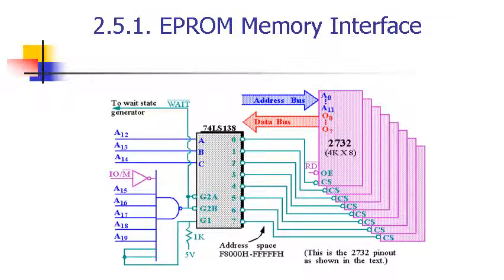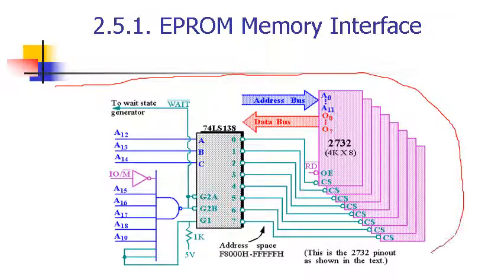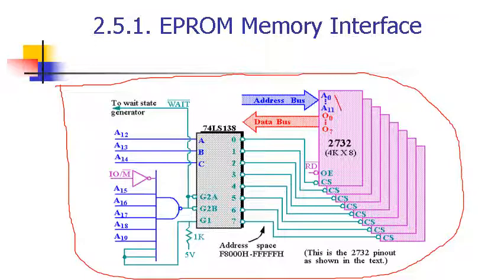And here is the final system. All right. First, A0 to A11, 12 address bits are brought through your address bus to each of these chips. So we're consuming now 12 bits of your address. How about the other 8? The other 8 are used as such.